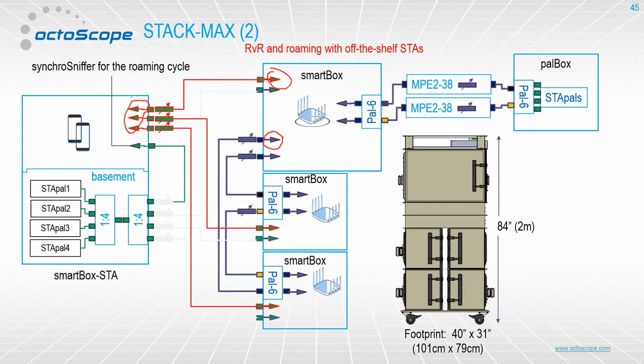This thing that I just circled here represents 2 antennas, and the reason it's 2 is because most station devices are 2 by 2. So we can support the maximum number of spatial streams in any link in these test beds. If you're looking to make sure that you can do a 2 by 2 link, for example, between here and here, the answer to that is definitely yes.